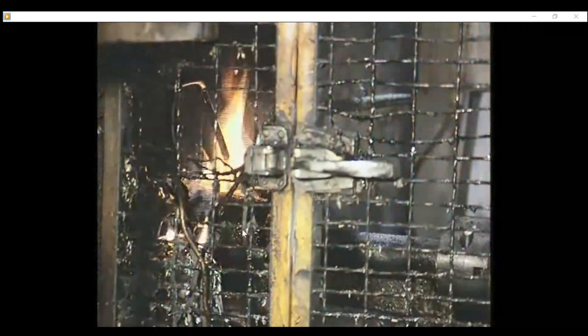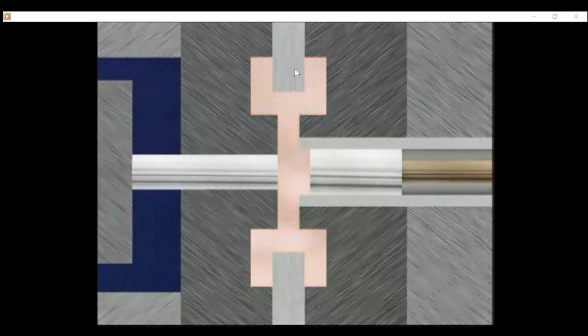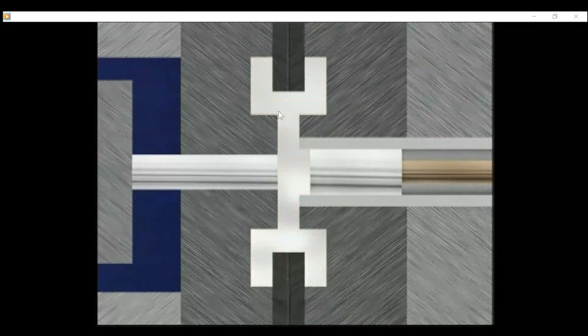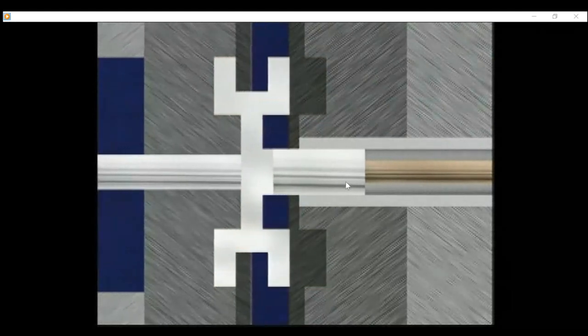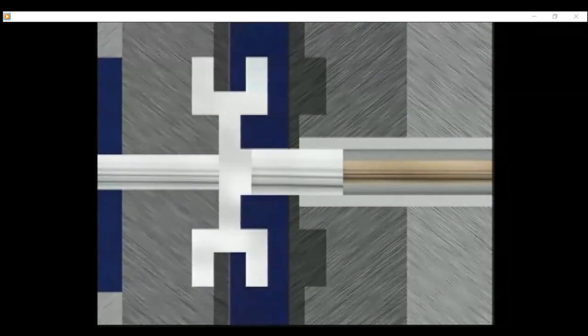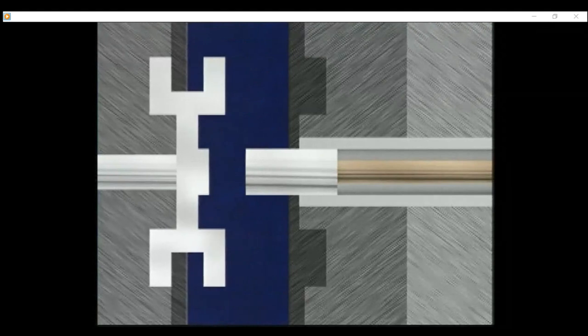So this is a plunger as you can see here. After you put the liquid, the plunger here pushes the liquid to fill all the cavity as you can see. After solidification, it takes the part out, and then this one will release, and then you start the process and repeat the process again for several times.